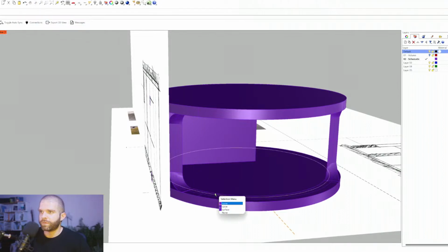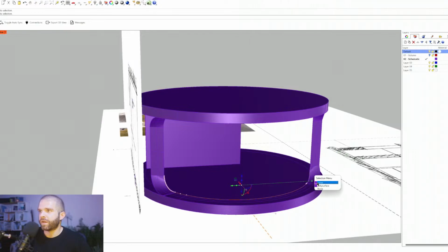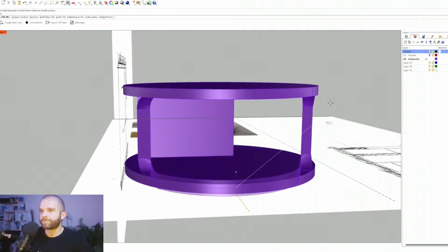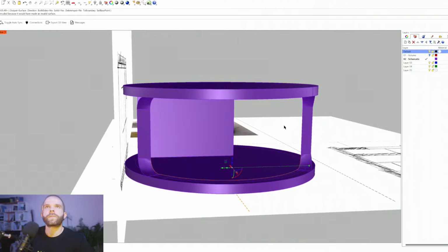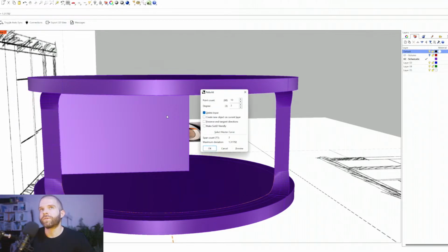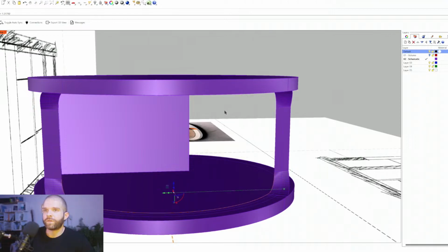But for the sake of this model, it can be like this. That's screwed up. I tried extruding up. Maybe I didn't join them first. Yeah. So I want to join all these curves together first and then do extrude curve. There we go. So it extrudes upward. One input was not extruded because it would have been an invalid surface. All right, that's fine. We'll do rebuild curve. Or just rebuild? Yeah, just rebuild. And how many points do we want to rebuild with? We'll do 50 to stay precise. Now we should be able to extrude the curve.